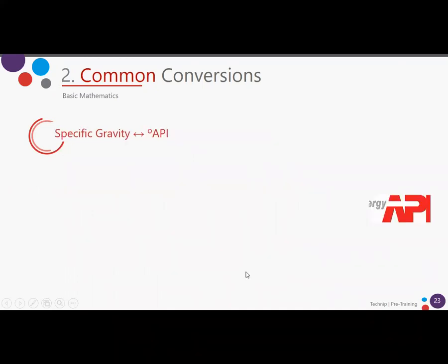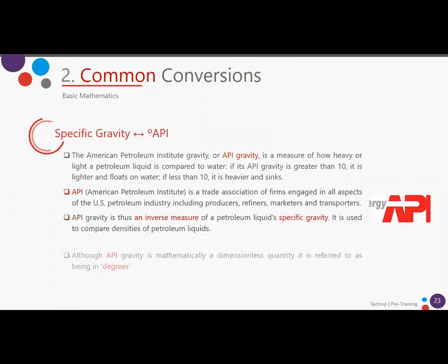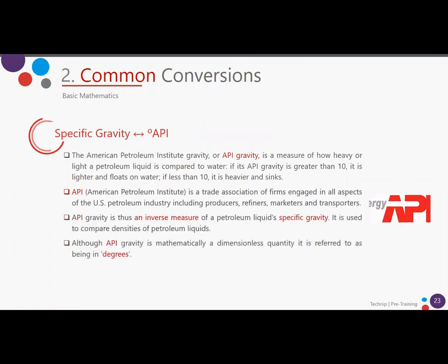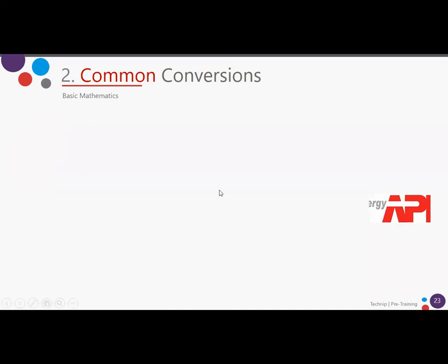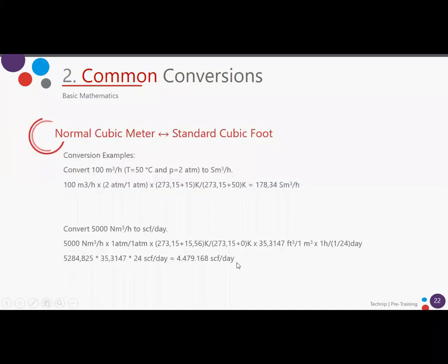Okay. Yes, Miss Emily, sorry. There is a direct conversion factor between standard cubic feet and normal cubic meter. It's 0.9. We just multiply. Okay, that's easier. Yeah, that's true. Okay. I can add that as a note. Good point. Thank you very much.